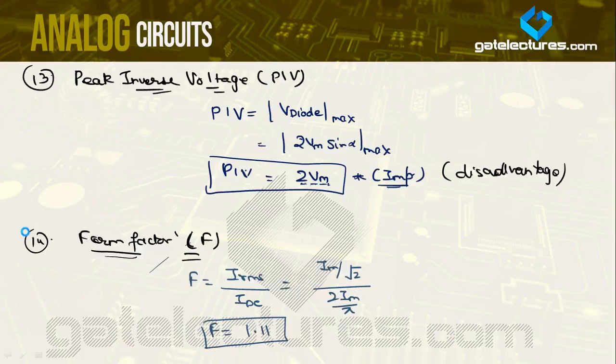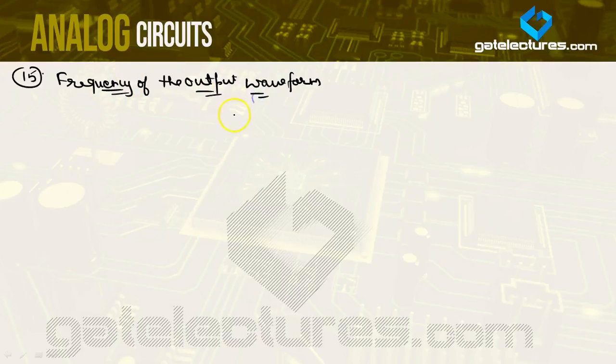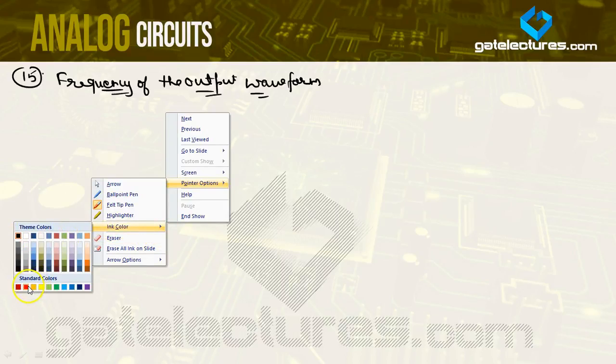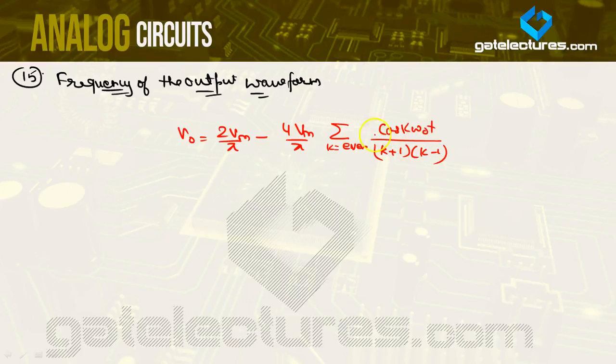Now the next point of discussion is the frequency of the output voltage. If we represent the output signal in terms of its Fourier series expansion, we get V naught equal to 2 Vm by pi minus 4 Vm by pi, summation k being even, cos k omega naught t upon (k plus 1) into (k minus 1). This is how you represent it.